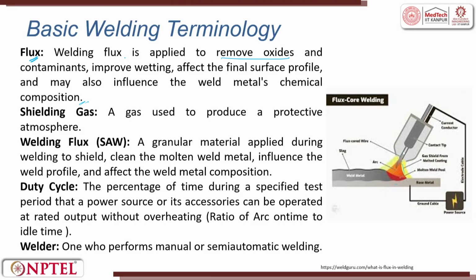It can do both. Flux removes oxides and contaminants which are formed while the reaction and melting are happening, and it also improves wettability or wetting.